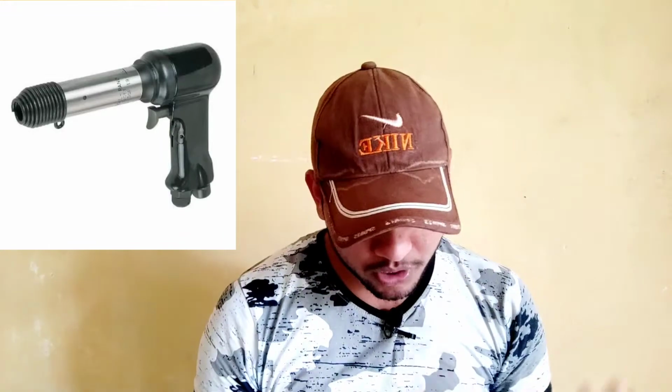The next tools are power tools. Power tools use pneumatic power. Pneumatic power is the air pressure they are using for riveting. As we are using rivet sets in the hand tools, in the same way we are using rivet guns in power tools. They are totally pneumatic. They are using air pressure and they operate at 90 to 100 psi. The pressure will be 90 to 100 psi. The slow hitting which we use is approximately 900 to 2500 blows per minute, meaning in 1 minute they can hit the rivet approximately 900 to 2500 times as required by your operation. You can choose the pressure.